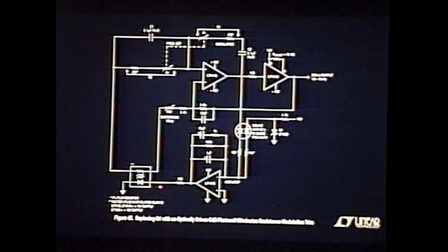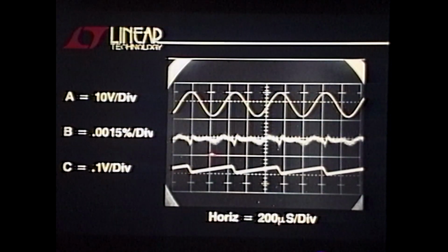The FET's gone. This is a LED-driven photocell. So the LED is driven by current out of the gain control amplifier. You generate light, that impinges on the photocell and changes its resistance. Why do I want that? Because there's no channel resistance there. There is no channel, okay? There's no coupling of any form, okay? And that concern just drops out. So you build this thing up, you get the same distortion now, you got rid of the gate trim, so that feels pretty good. You've got an architecture that's inherently a little better in that regard.